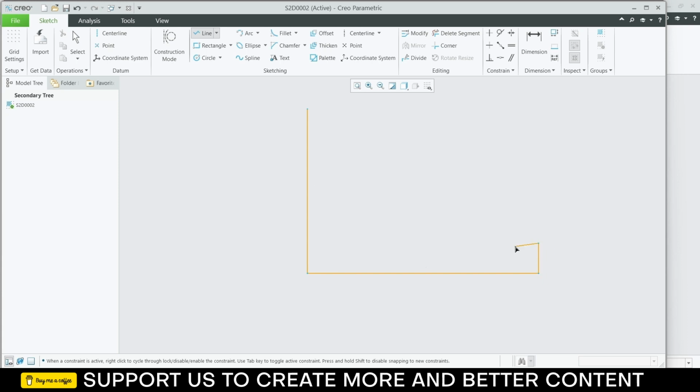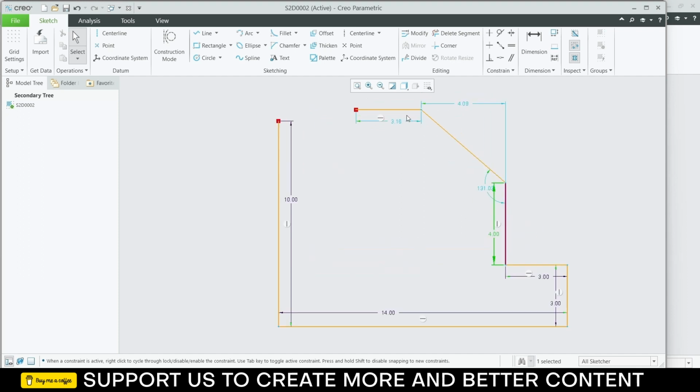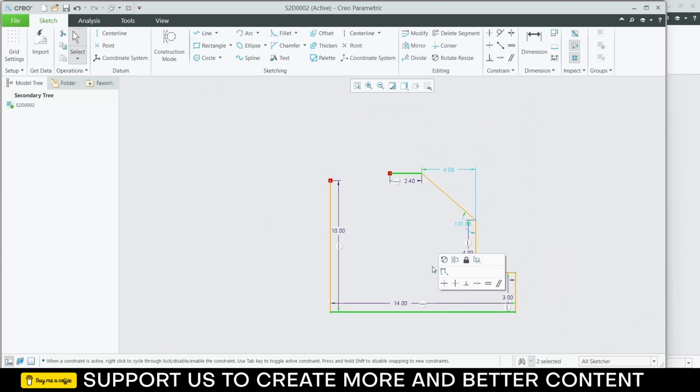Now I'm drawing some rough sketch. Click on the middle mouse button, click on the middle mouse button again. So this distance will be 3. This one will be also 3. The length is 4. And this is 2.4. Select this. By pressing Ctrl, select this line. Click on dimensions. This will be 10 mm.